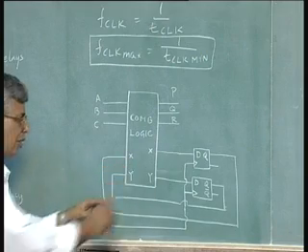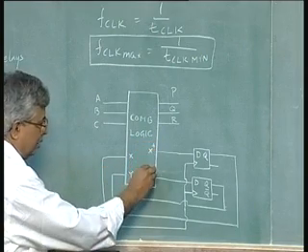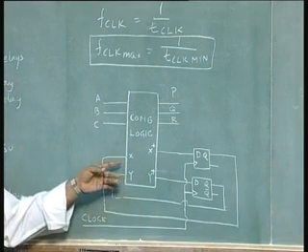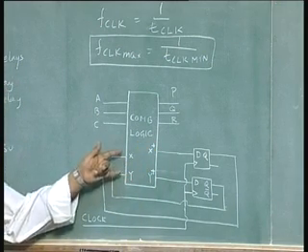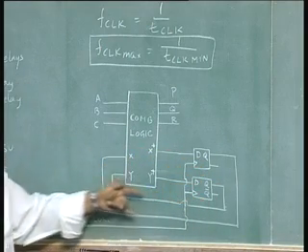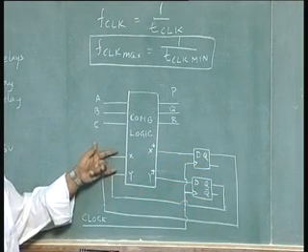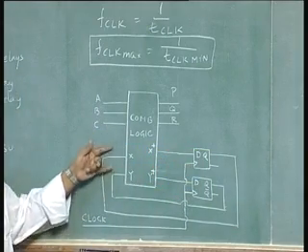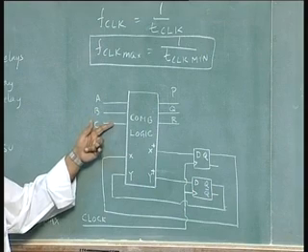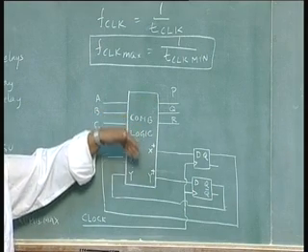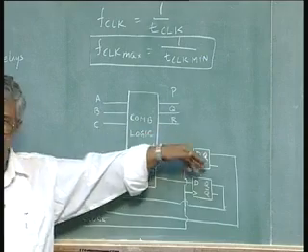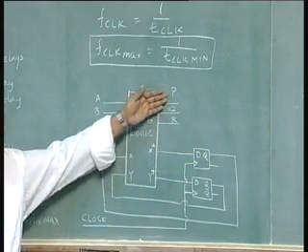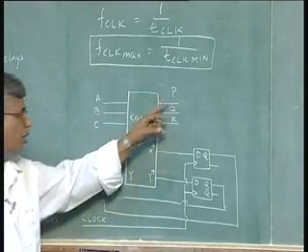In order to distinguish between these two, usually people put a plus on this, x plus and y plus, indicating it is the next state. So, given a set of inputs x y which are the state inputs, the output during the previous clock period, along with the combinational inputs a b c, we get x plus y plus, which are going to be the next state inputs or outputs as the case may be, and p q r are the external outputs. These are called combinational outputs or external outputs.